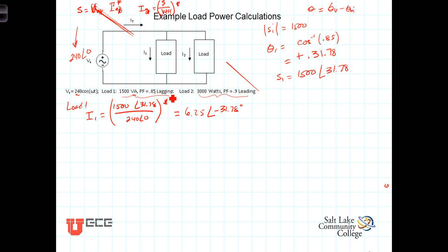Now, while we're at it, let's just go ahead and calculate what the impedance of that load is. We don't need it, but let's remind ourselves that that load really does have a resistance and a reactance. Z is, by definition, always has been and always will be the ratio of the phasor voltage to the phasor current. It doesn't matter whether it's effective or not, but since we're working with effectives, we'll use effective voltages here.